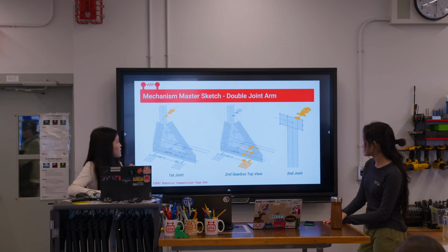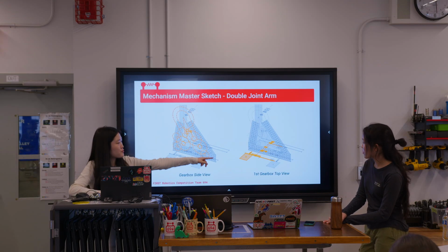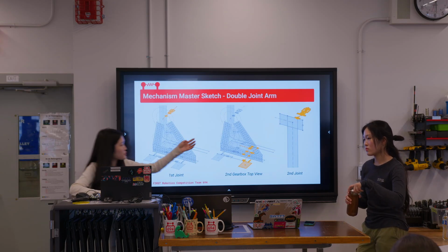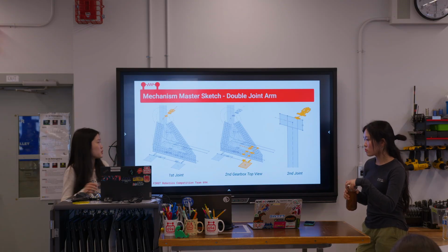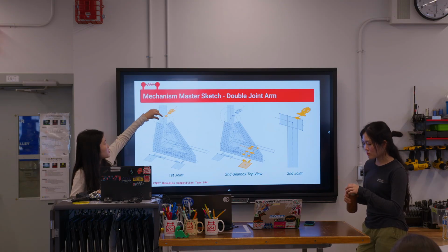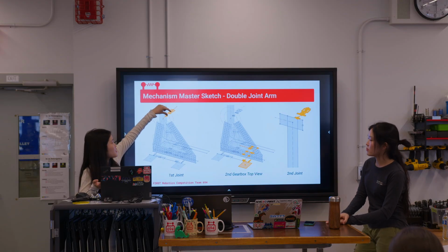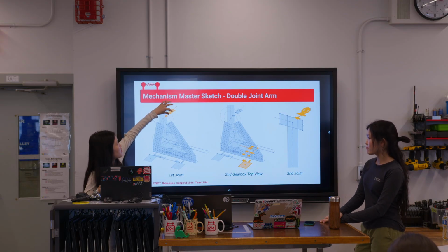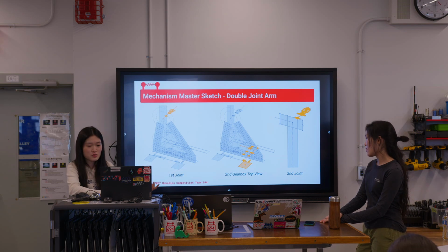And then next, instead of the flattened view, some of these axles, such as the joints, the first joint and second joint, have their own axle sketch, which we're going to go into more detail about. It also represents the distance between each of them, because I want to know where the pulley for the second joint is going to go, where the tubing for the first joint is going to go, so all that distance is represented, and also another flat view of the second gearbox, which is just the second joint.